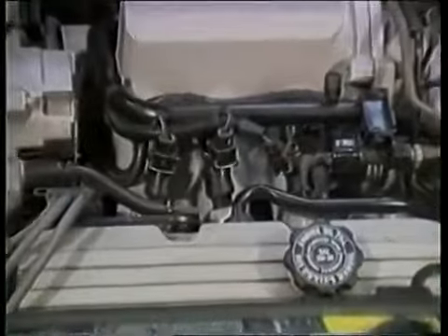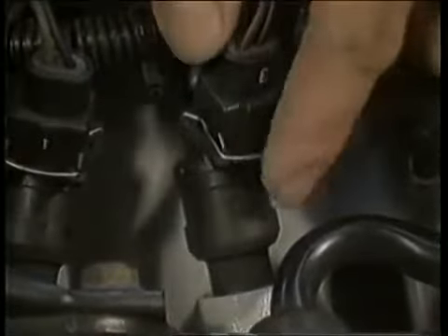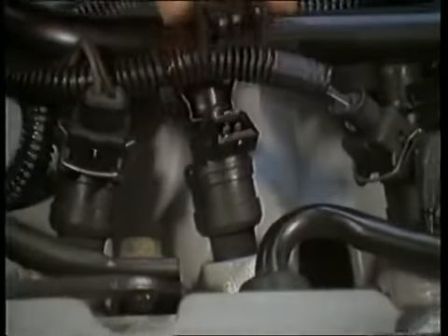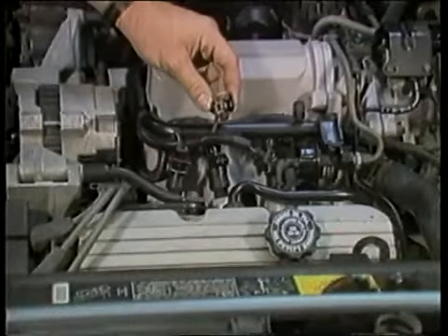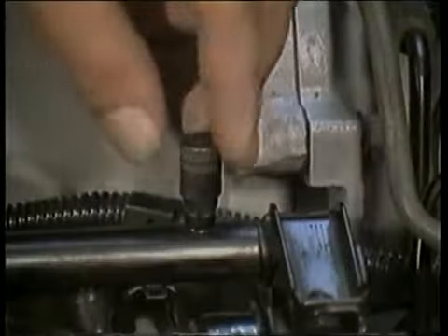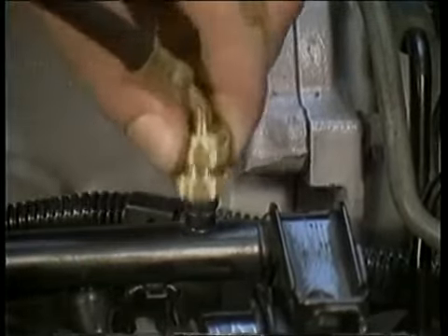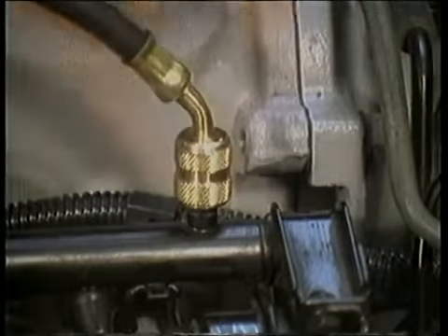To connect the tester to a vehicle, disconnect the wires going to the injectors and swing them out of the way. Then, fasten the tester harness wires to the injector terminals. Connect the tester fuel line to the fitting on the fuel rail. Follow specific equipment instructions when connecting the unit.